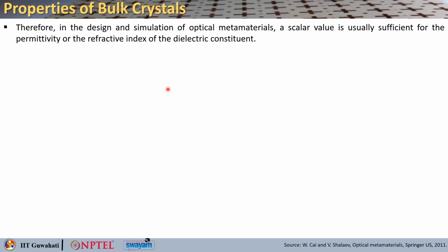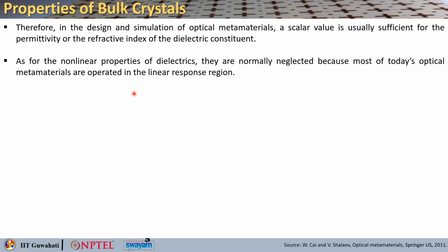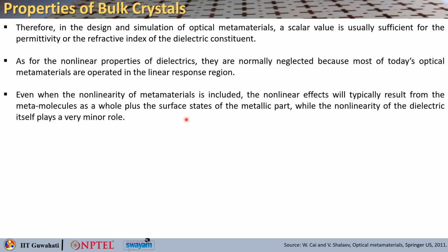Therefore, in the design and simulation of optical metamaterials, you can assume a scalar value, which is typically sufficient for the permittivity or the refractive index of the dielectric constituents. The nonlinear properties of the dielectrics are normally neglected because most of today's optical metamaterials are operated in the linear response region.